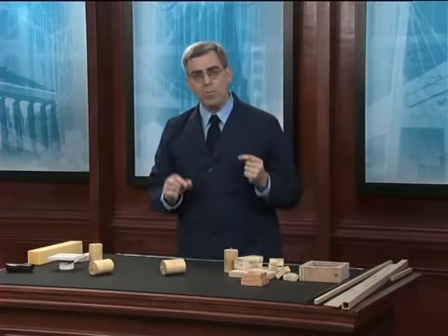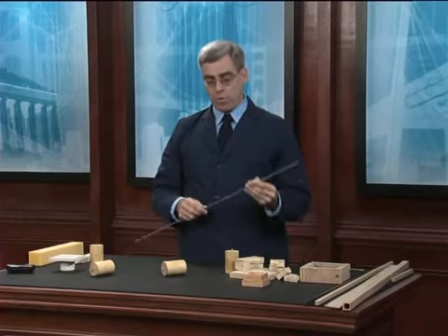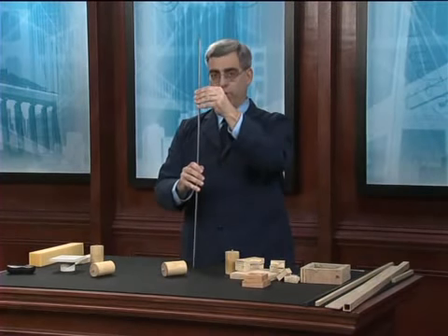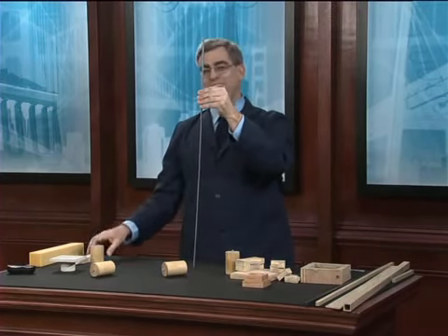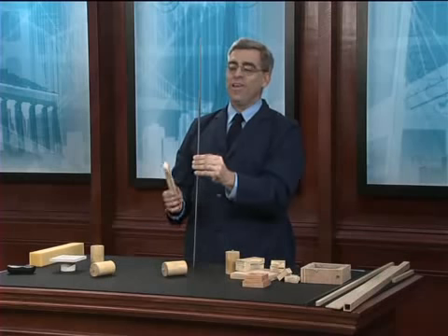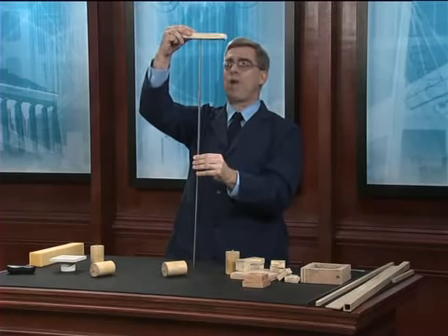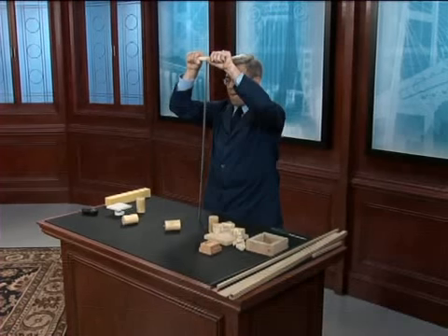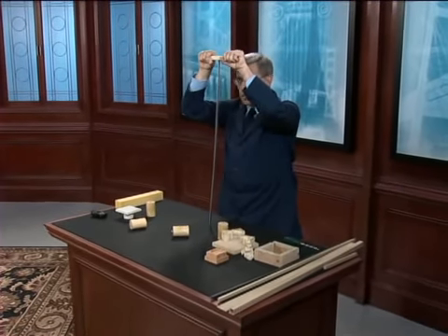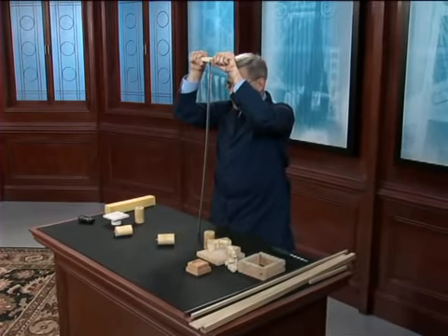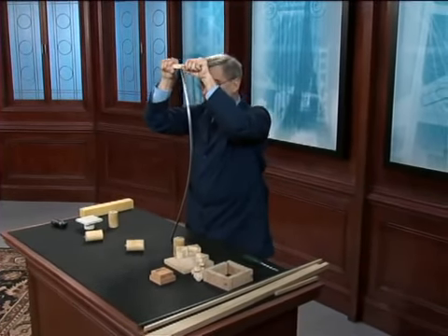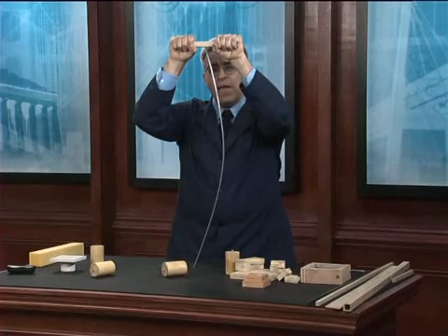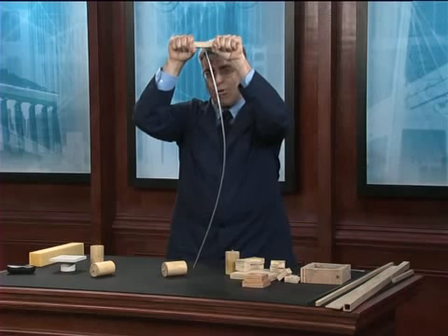Now, buckling is a failure mode that occurs when a member, and in this case, I'm going to demonstrate it using a member that will buckle in a slightly more controlled mode, when a member is subjected to a gradually increasing axial compressive load. And even though the load is purely axial, at some point, the column suddenly deflects laterally. And that deflection is often quite catastrophic.